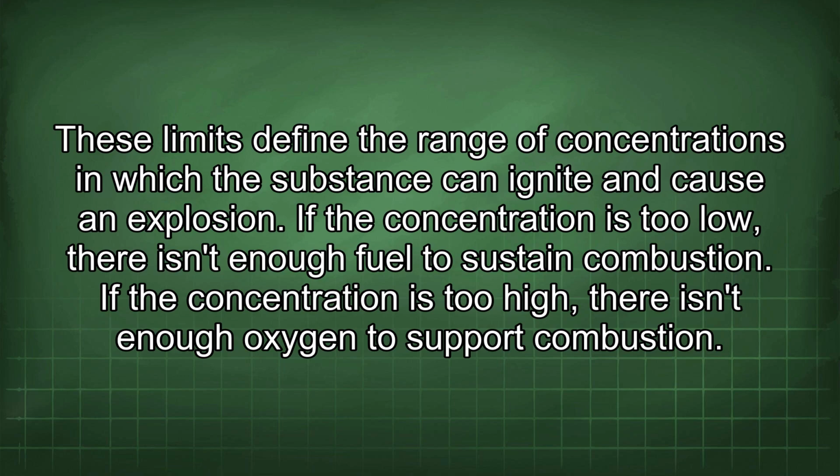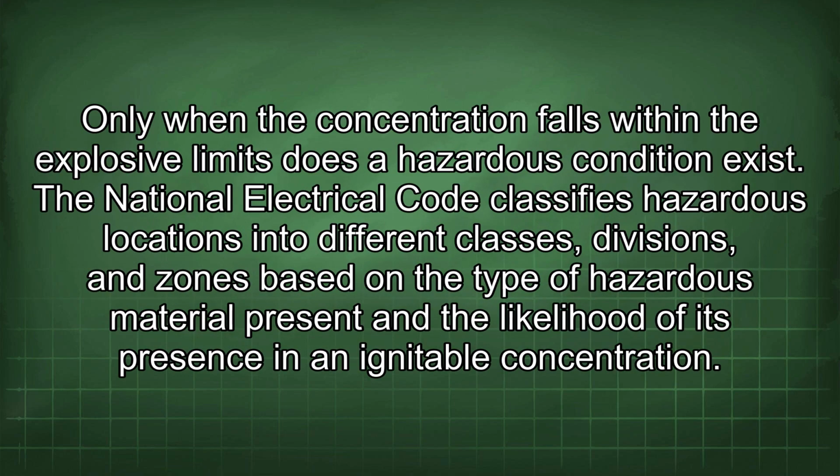If the concentration is too low, there isn't enough fuel to sustain combustion. If the concentration is too high, there isn't enough oxygen to support combustion. Only when the concentration falls within the explosive limits does a hazardous condition exist.